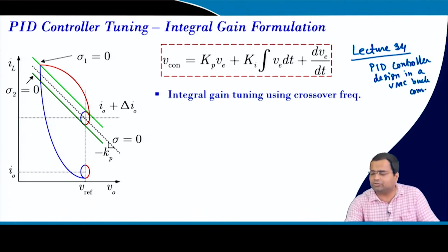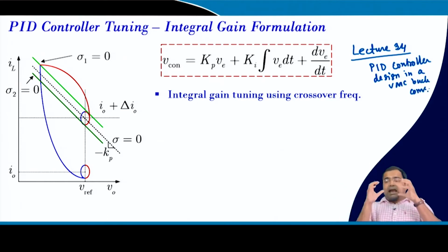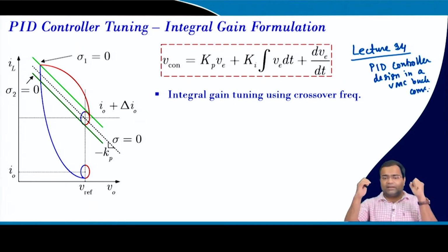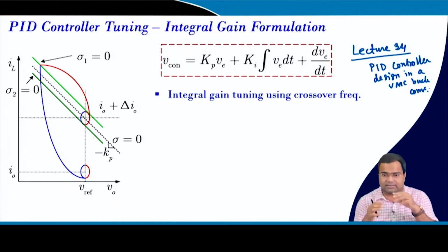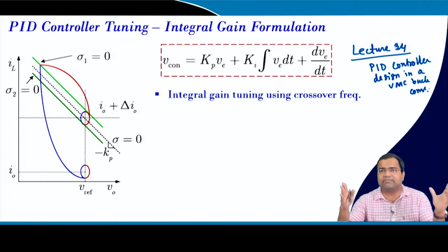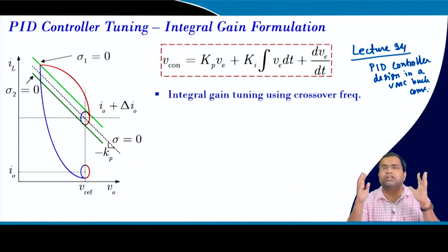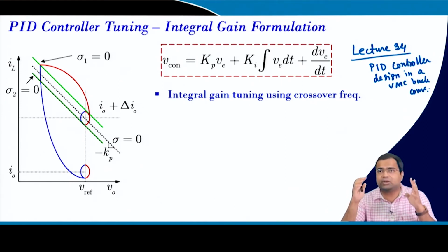So, that lecture talked about PID controller design, and there we found if we use a PID controller, we can by means of an analytical stable pole zero cancellation get a first order closed loop equation. But unfortunately, we could not get suitable model matching even up to 1/10 of the switching frequency. Our model was limited. So, that is why we are considering this PID controller gain.